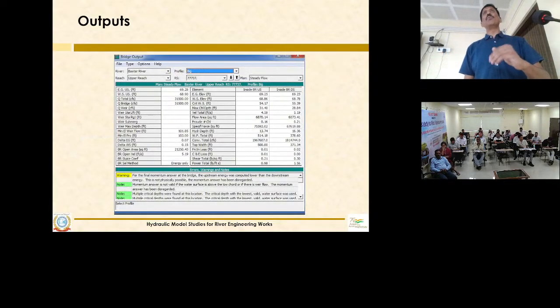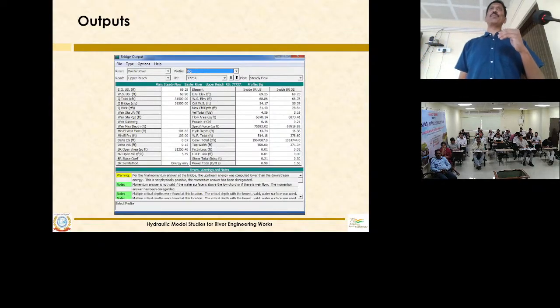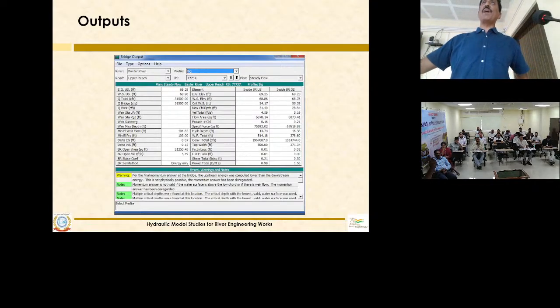And you get the more detailed version. In a cross section, if you want to see the various properties, the hydraulic depth and everything that is required for the sediment computation, it has given more detail. So what is the flow area, weighted depth, and all these things. If you are placing a weir, what is the flow passing through the weir, what is the flow passing through the lateral weir, that distinction we can also get from this.